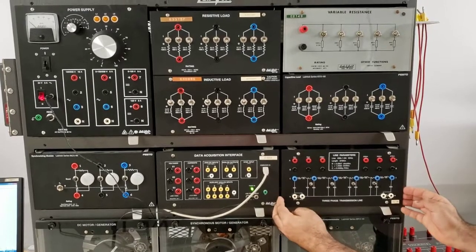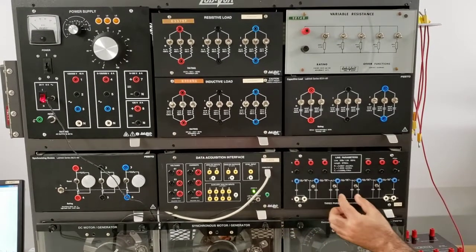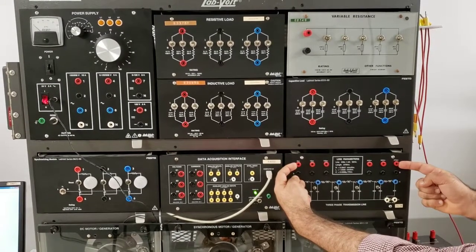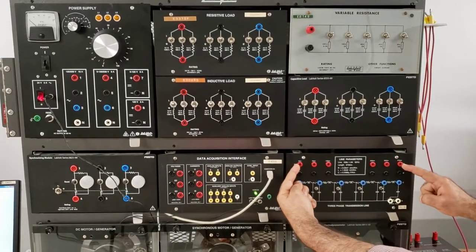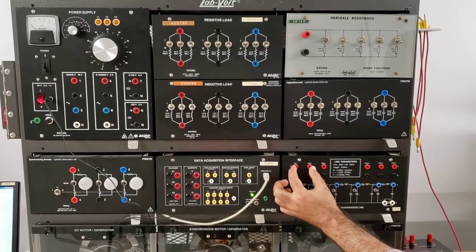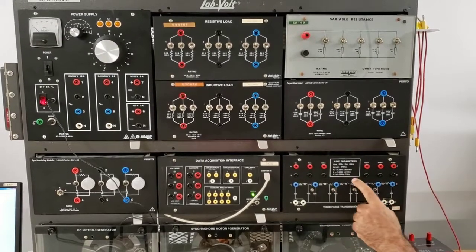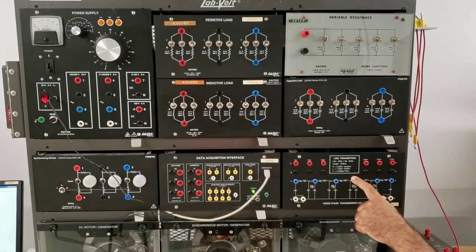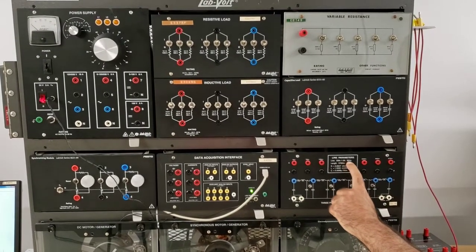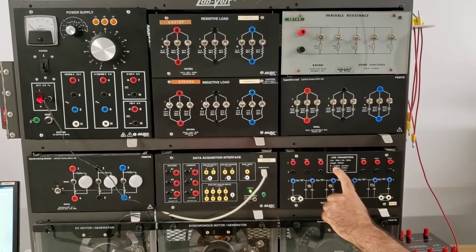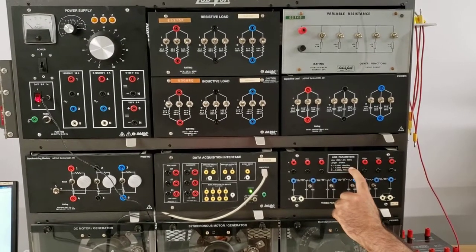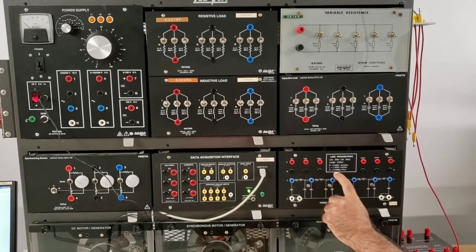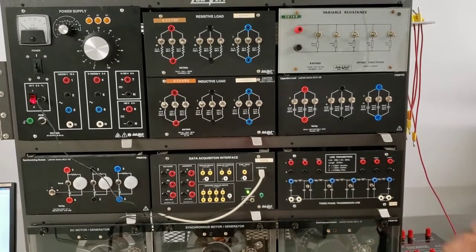use. This model has 5 different sections of pi. They are connected in series. And the length for this transmission line is 375 kilometers. So each section has 75 kilometers. As you are seeing, these are the ratings for the transmission line. The line voltage is 208, the current is 1 ampere, the frequency is 60, and the resistance is 0.0947 ohm per kilometer. The inductance is 1.33 millihenry per kilometer, and the capacitance is 0.0088 microfarad per kilometer.